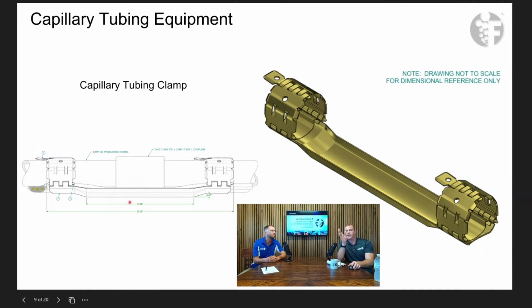So you're saying if you see 10 degrees of inclination or greater, you want to run clamps across that section? That's correct. Okay. Well, and remember, it's not just across the section, it's from that point down. Because everything's got to run through that. Gotcha. Okay. So, sometimes on these multi-well pads, we might have an early or shallow kickoff at say 3,000 or 4,000 feet. Yep. And then it's going to run at an angle for a while and then kick off to the horizontal section. So you're saying across that piece, you're going to run clamps. That's correct. Okay. That's good to know.